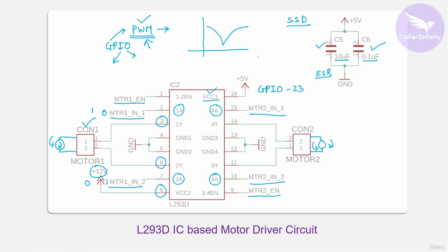The reason is it depends on the power supply that you are using, and also on the noise or the ripples which are there on the output side of that particular power supply. If your power supply is pure, with very little noise on the output side, then you don't have to connect the capacitor in order to filter out that noise. But if your power supply is producing a noisy +5 volt signal, then you have to check on the DSO what the frequency of those ripples generated by your power supply is, and accordingly you have to select a suitable value of capacitor.